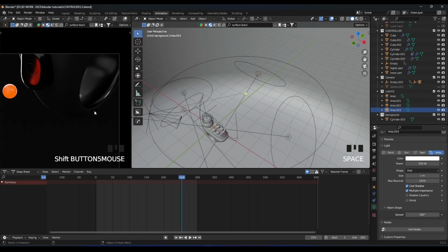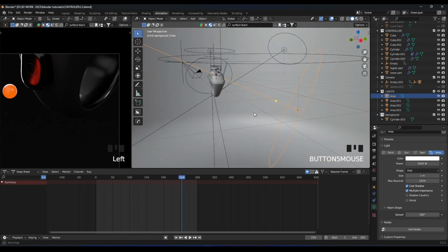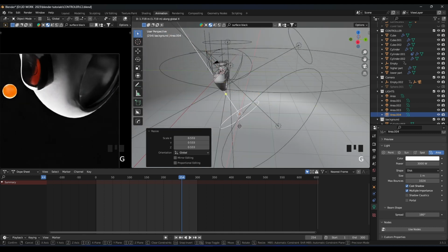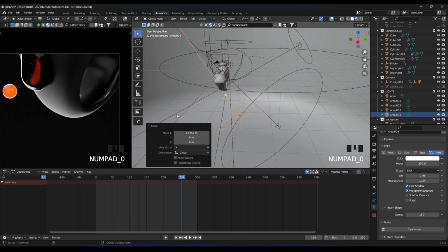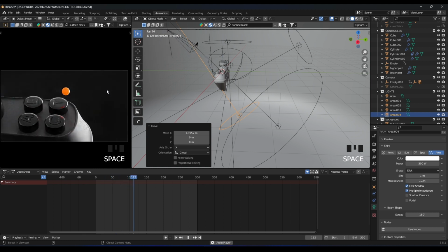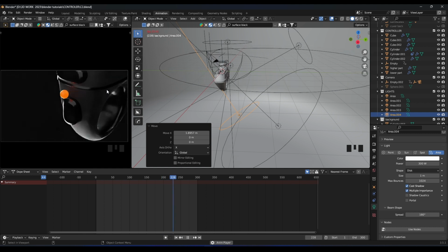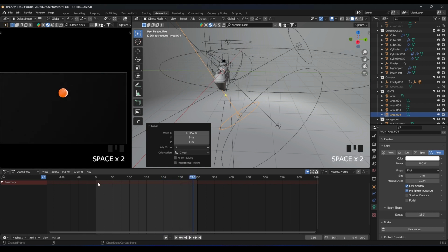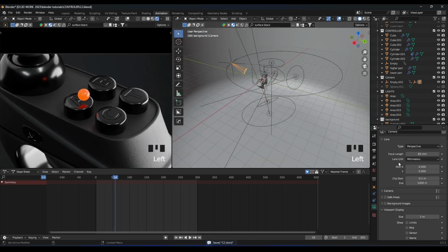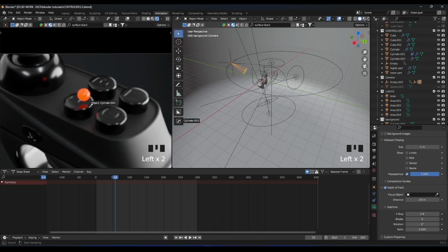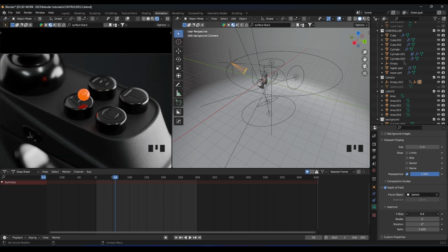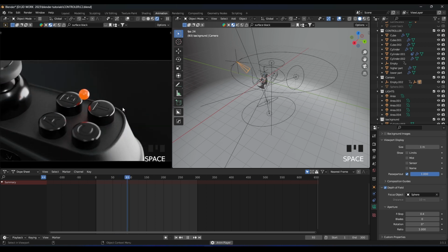Okay, nice. And we need a little bit of rim light down in this part. So let's duplicate this and move it here, rotate it again, move it right here, scale it like this, and we need it to be 300. Let's see. Okay, nice. I guess what we need to do more is just to make this a little bit realistic. I think we're gonna add some depth of field like this, and we're gonna follow our sphere, maybe 0.5 or 0.4. Let's see right now. It's looking very nice.